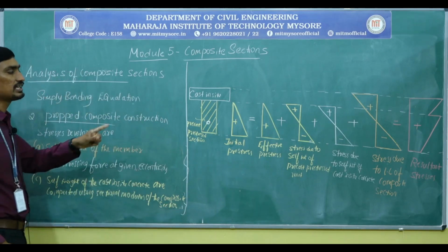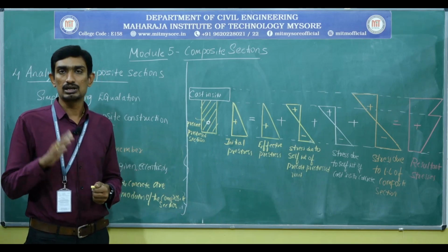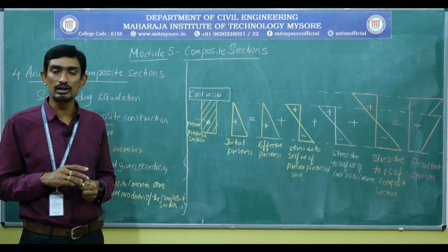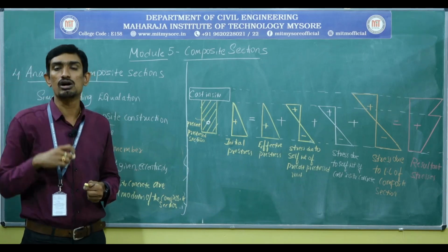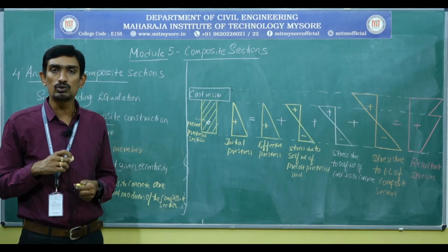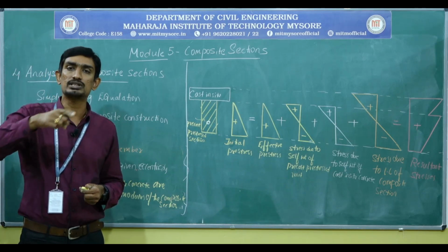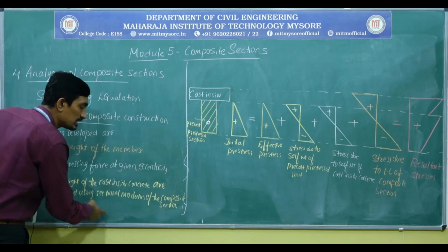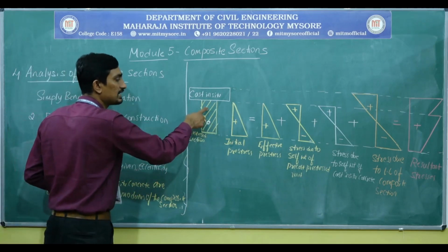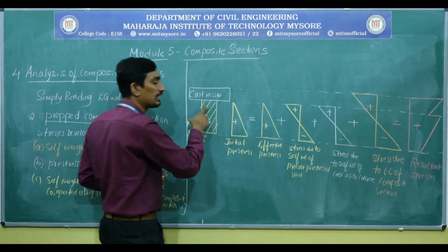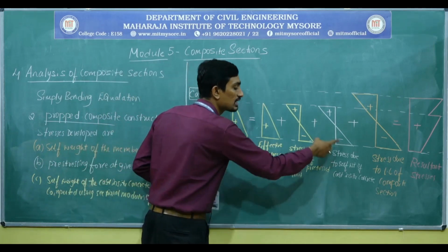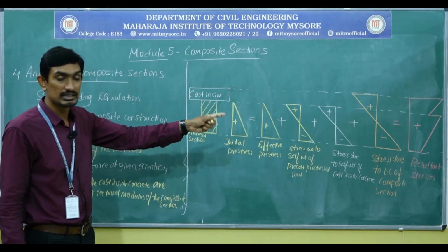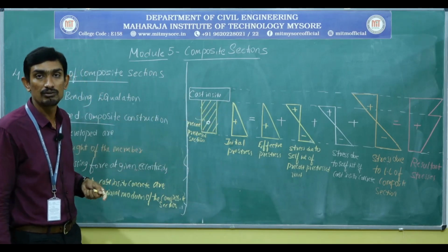Okay, this is the one change in the case of propped case. Because of providing props to the precast pre-stressed unit while placing the cast in situ concrete slab, I am going to consider the entire composite section. That is, the sectional modulus of the composite section will be considered in order to compute the stresses developed due to the self-weight. So because of that, the stress diagram will vary. I will write down now how it will vary.